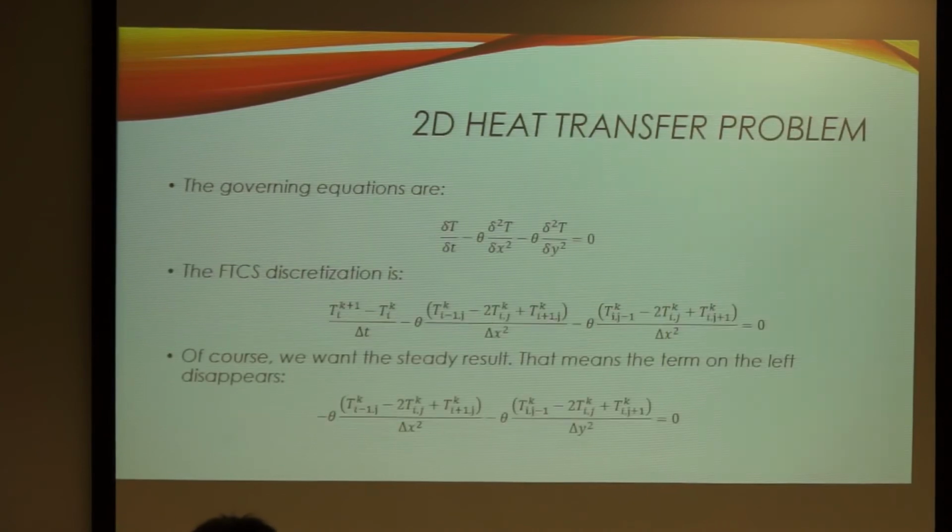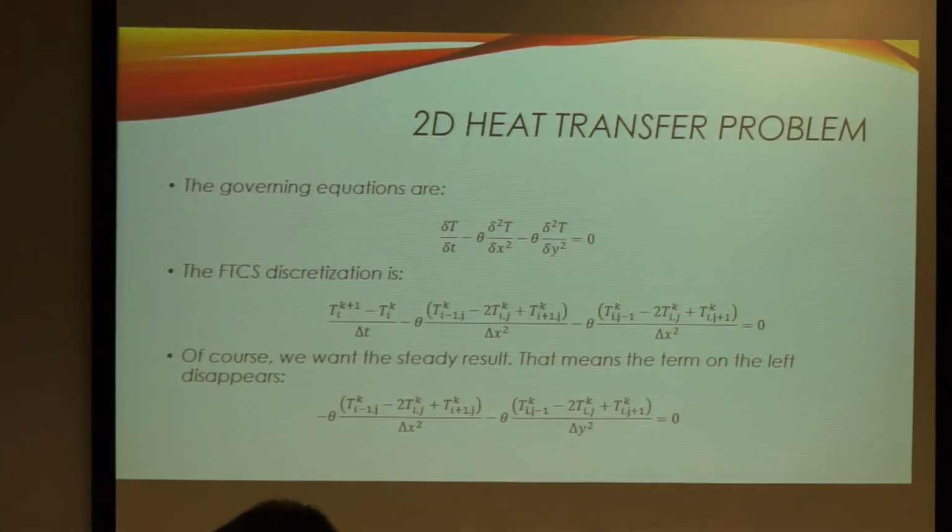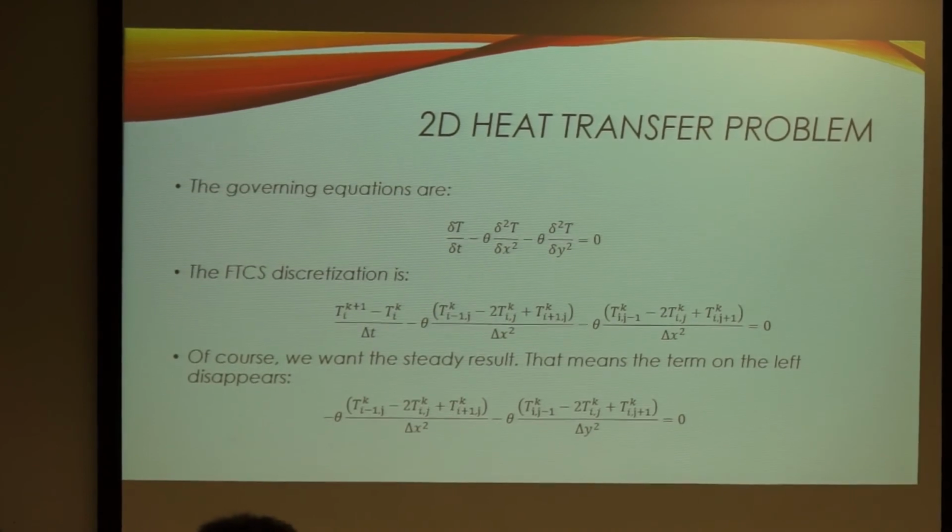We needed to compute the steady temperature distribution. Here are the equations we used. So we did explicit transient FTCS last week. So we had an FTCS discretization with a time derivative on the left, and we had all of our spatial discretizations in the middle here. That's d y squared by dy squared, but I did fix it up down here.